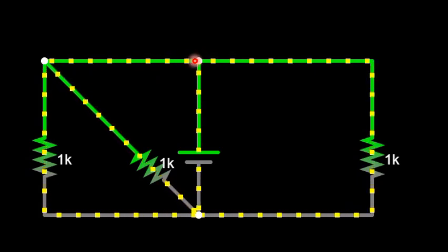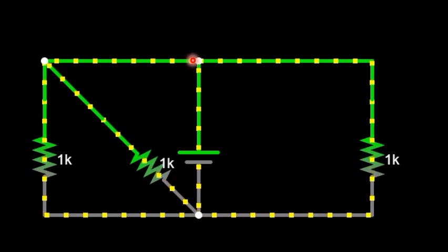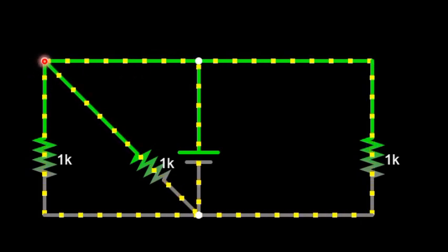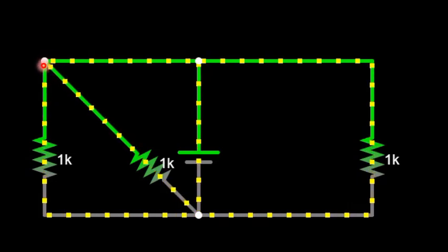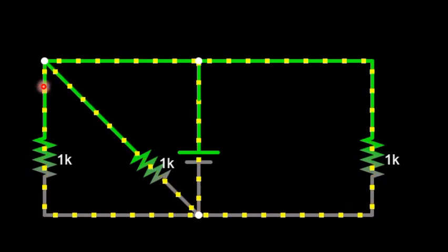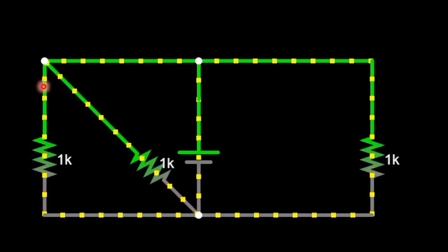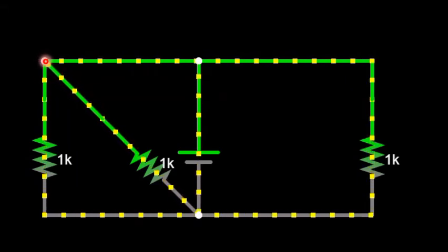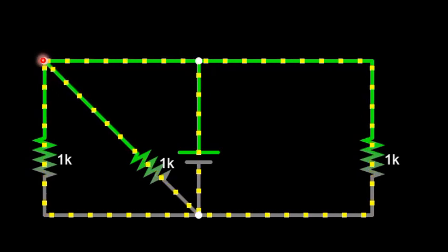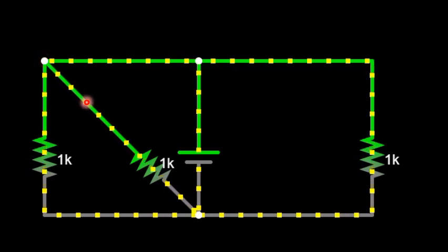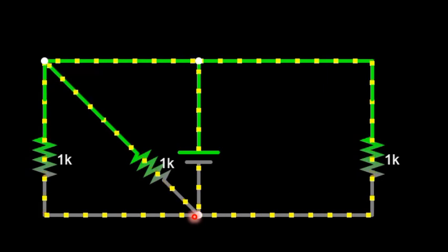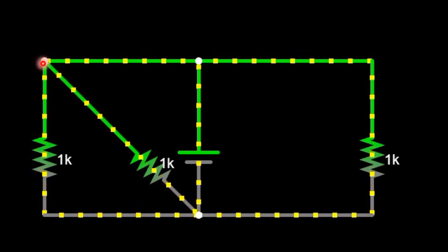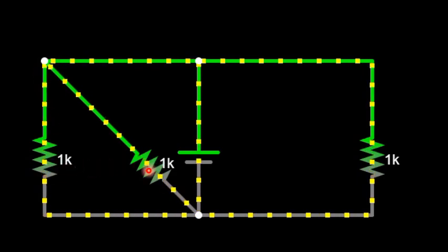Moving on forward, at this side too, you see that the current gets here, then splits. So let us use the trick I showed you to see whether we can identify the parallel networks. Here, when we circle from this node, we can circle through this resistor all the way back here. We didn't meet any third element, meaning this and this are in parallel.